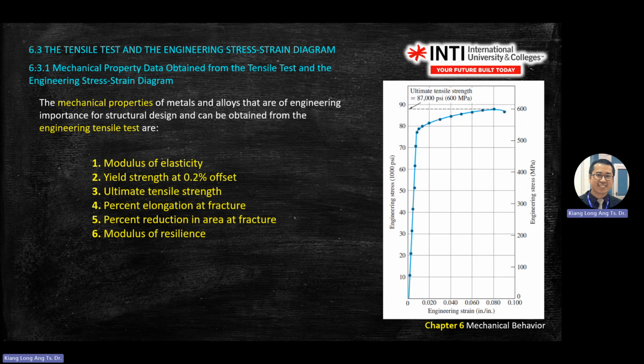What does the 0.2% mean? It goes to the strain here and it multiplies. So 0.2% equals what value in decimal? 0.002. Correct. You convert 0.2% into decimal and it is 0.002. You know how to calculate strain, right? So strain also gives you a decimal. So what you do, you go to the bottom of the chart and find 0.002.